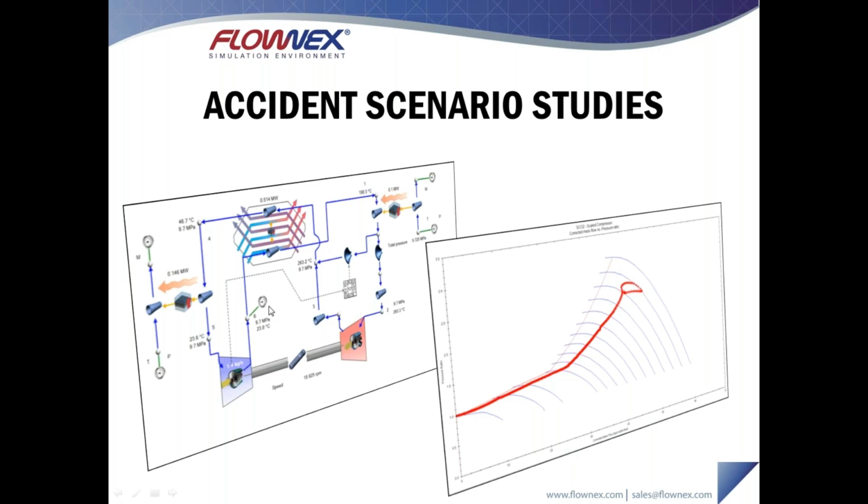What we'd like to do in our shutdown here is ensure that the compressor and turbine slow down in a controlled manner and that the compressor never enters surge. The graph that you see on the right here is the compressor map, the characteristic compressor curves as you can see, and then the faint red line representing the surge margin. The thicker red line represents the trace of the operating points over time. It originally started up here on the third line from the top. It then shoots to the right as soon as the generator is decoupled because the turbine train increases in speed very rapidly. It then loops around and gradually begins to taper down towards its zero mass flow rate condition.